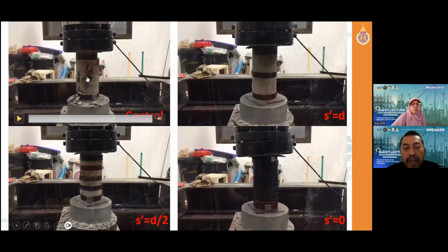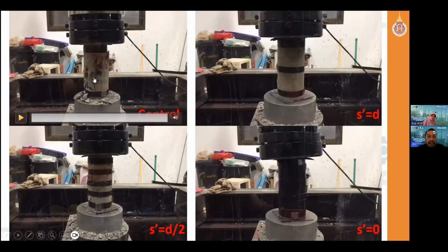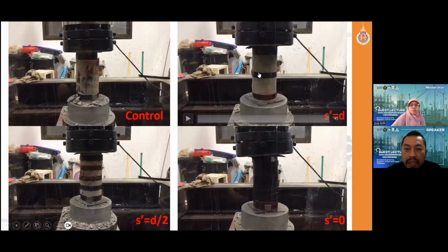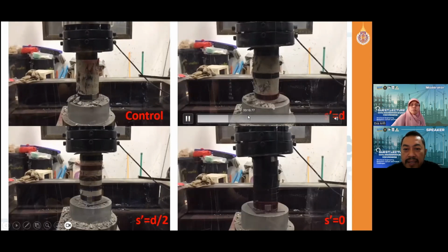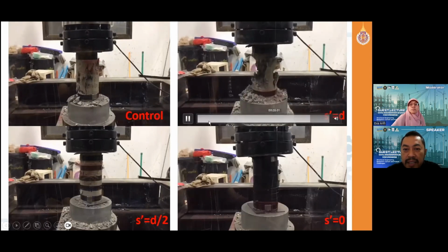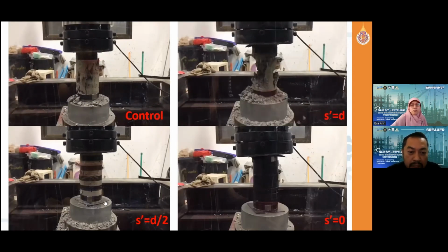So imagine this is the column under axial compression. It will crack like this. But what if we confine like this? This one, the capacity increased probably 5%, if I remember. Let's try to put more belts. The belt is made of steel.